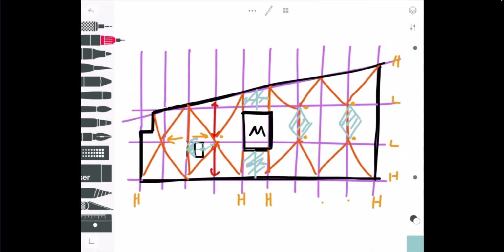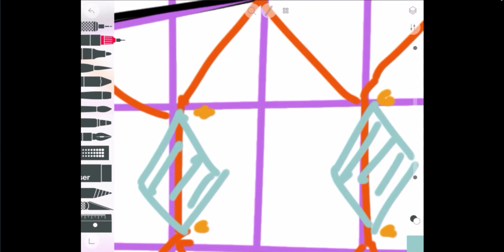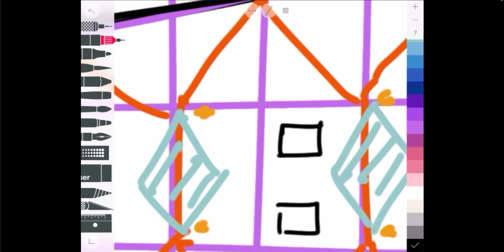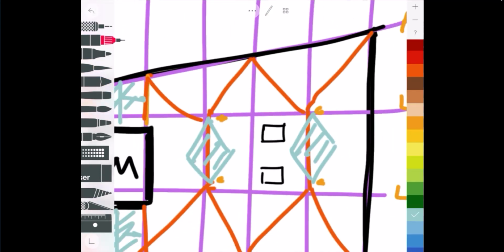And then over here, oh, I thought I had some rooftop units in here, but the same principles apply. So if we had a rooftop unit sitting right here, let's say, and right here, then again, you would want to just make sure that the slope goes around that rooftop unit so that there was a high point right here.